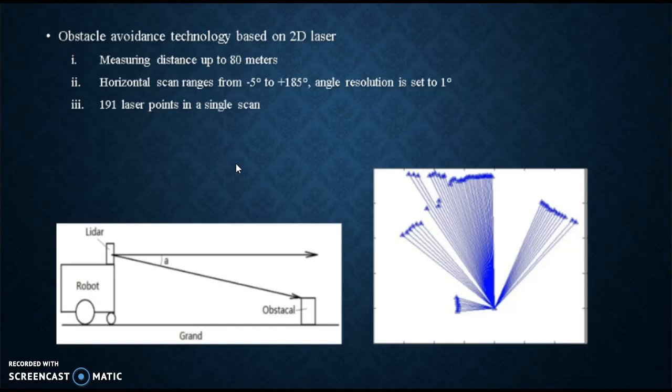The visual graph method can be used to judge if the line between the mobile robot and the target crosses an obstacle. No crossing means the target is visible, and the robot can reach the target point directly. Otherwise, choose one of the connecting lines from the robot to the end of the obstacles in the direction of travel.